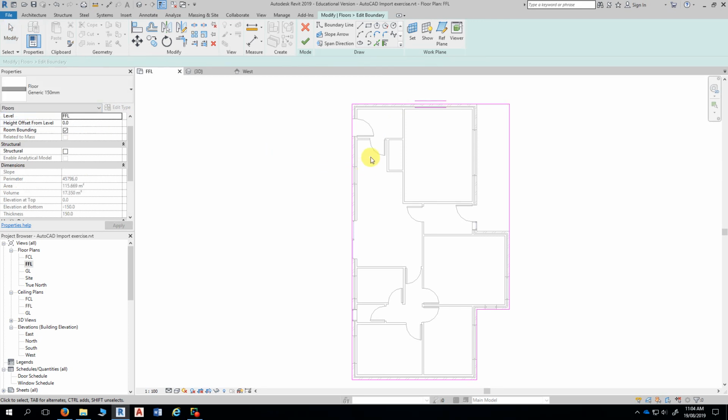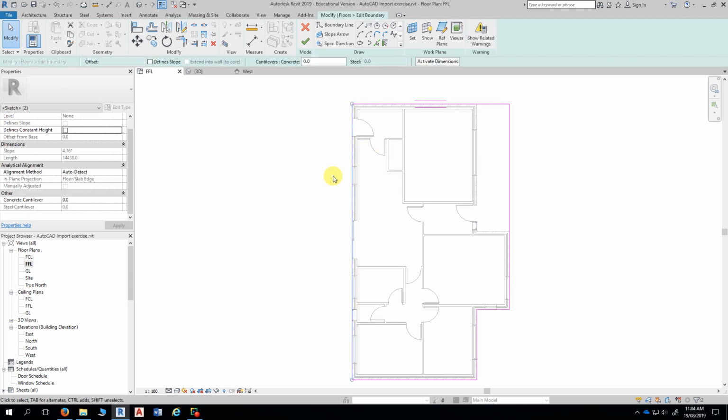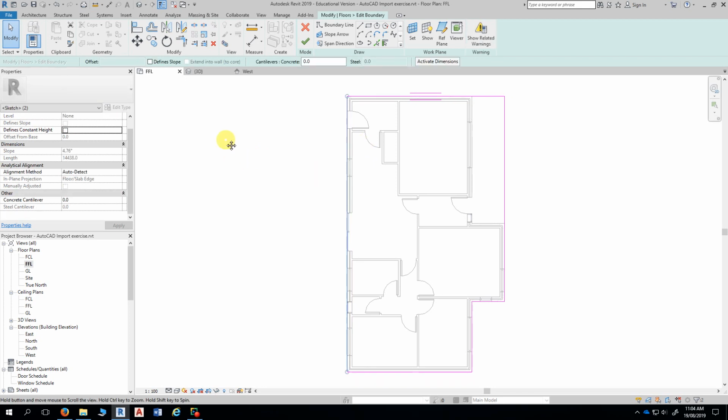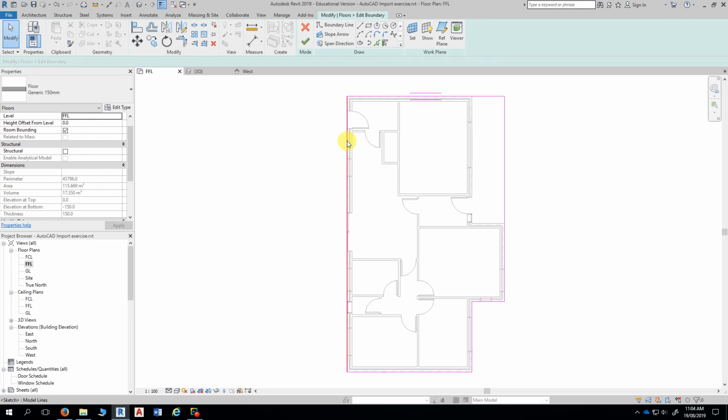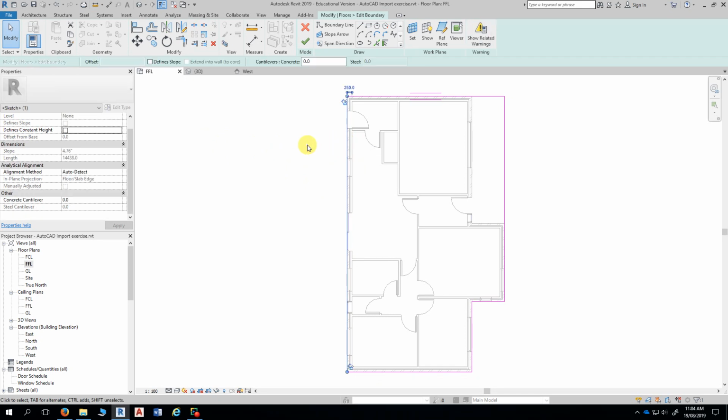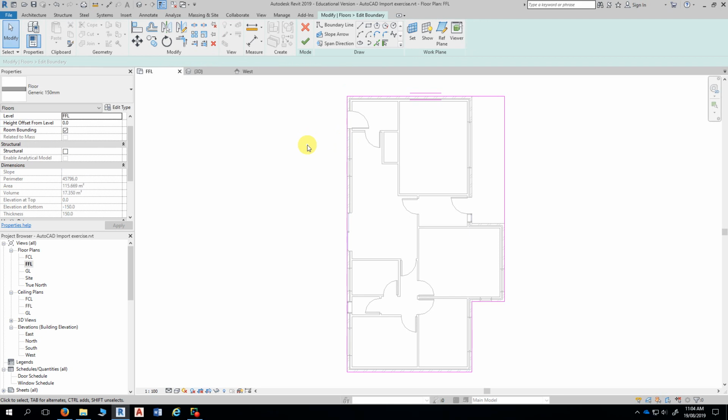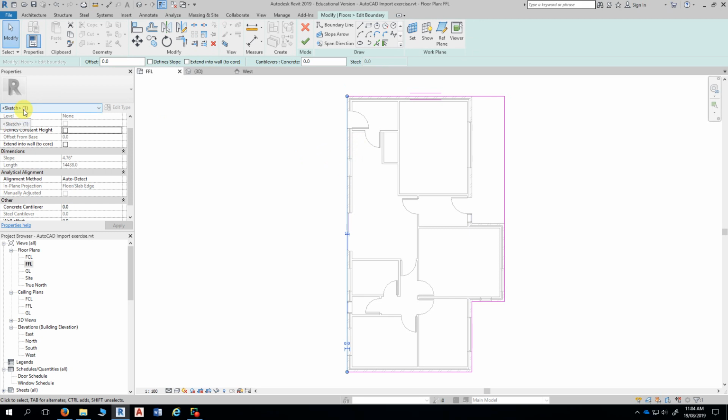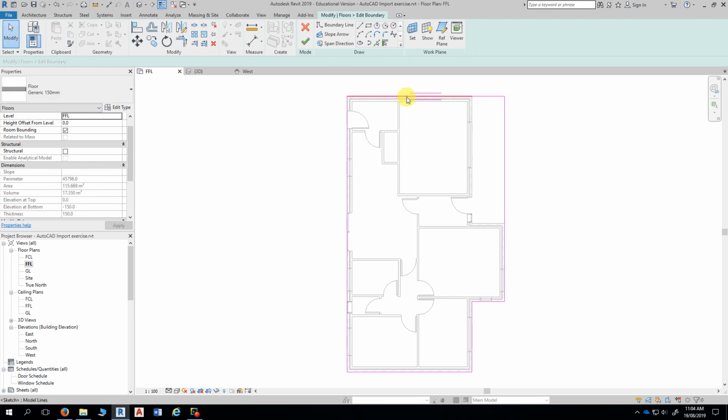This is part of the problem solving technique: if you suspect you've got double sketch lines, that's the way to test for it. I've got two here, so I'll click on one of them and hit delete, and that leaves one underneath. If I drag across there, I'm now back to one. So that's fixed that. Same here.